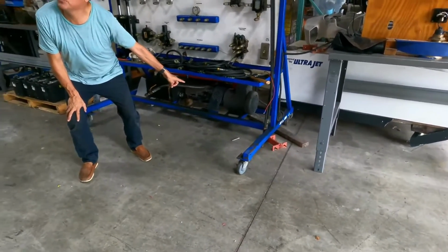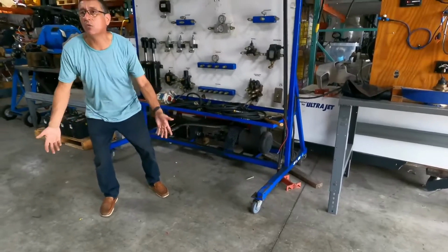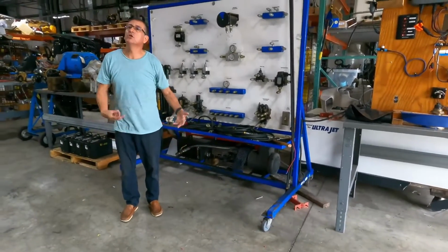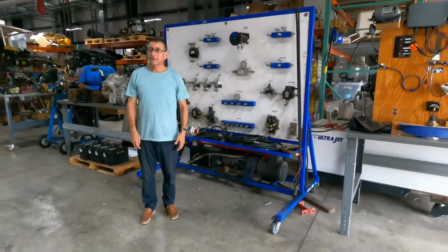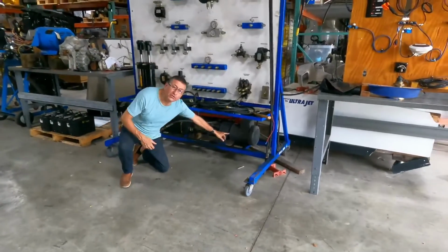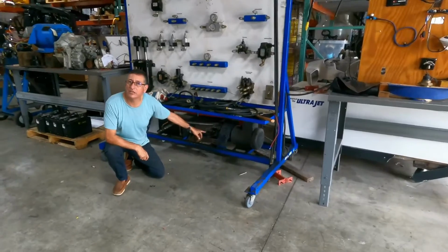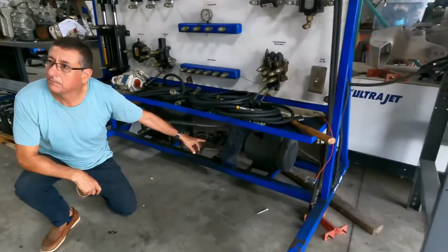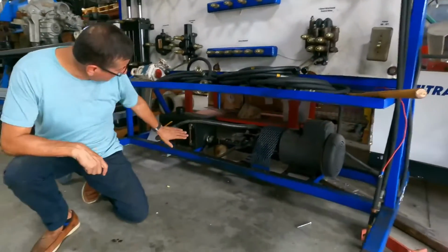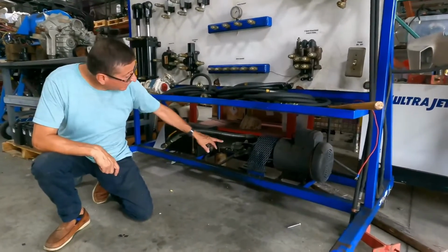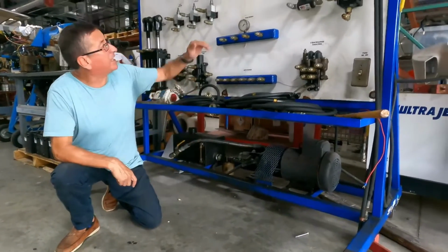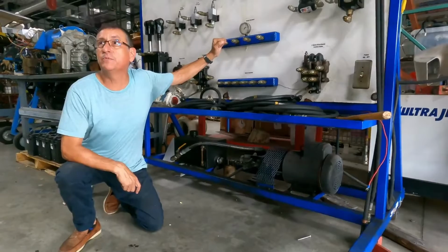That's okay? This is why I select that 3 kilowatt motor. Double phase, 240. I have the motor, double phase 240, 3 kilowatts. I have the pump, 20 gallons, 250 psi. And now I have the reservoir. From the output of the pump, I create the supply manifold, the positive bus bar.